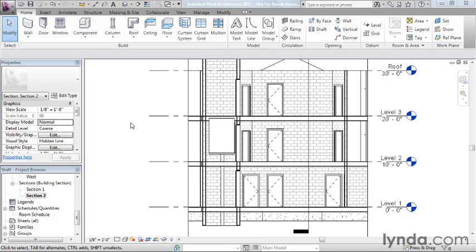Now, an opening object, there's a few different kinds that Revit includes, and they're basically all the same in the sense that they're all void objects, and a void object you sketch in a very similar way to a solid object. The difference is the void interacts with a solid object and actually cuts a hole in the host solid object. So let's go ahead and take a look.